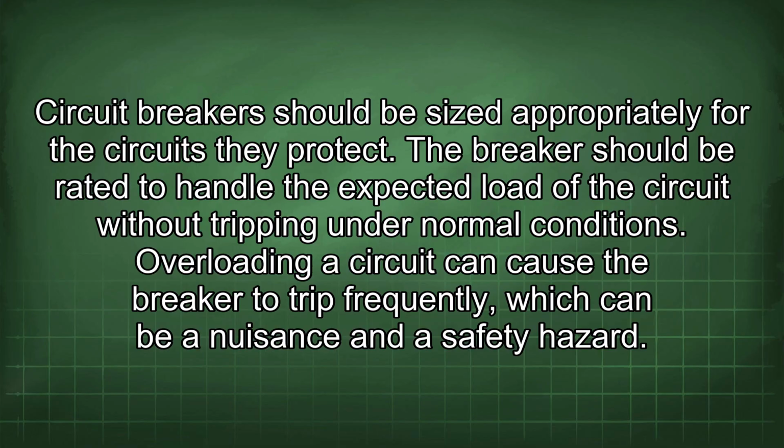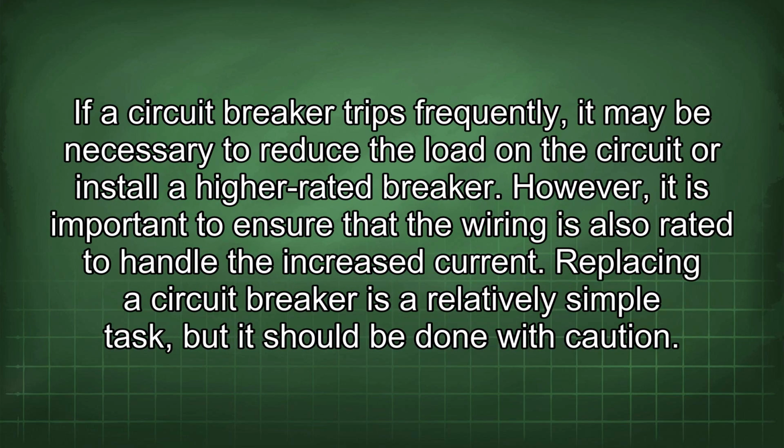Overloading a circuit can cause the breaker to trip frequently, which can be a nuisance and a safety hazard. If a circuit breaker trips frequently, it may be necessary to reduce the load on the circuit or install a higher rated breaker. However, it is important to ensure that the wiring is also rated to handle the increased current.